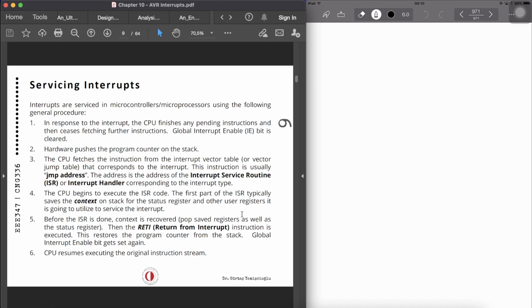We have to pass simple parameters to and from the subroutines, and local variables cannot be declared through absolute memory addresses. So it has to be done through the stack, because we have to use push and pop, and we have to retrieve or save the values in order not to lose them. So if you want to write programs with re-entrant subroutines, like factorials or Fibonacci, that call themselves recursively, we need to think about utilizing the stack to save the context whenever it's needed.